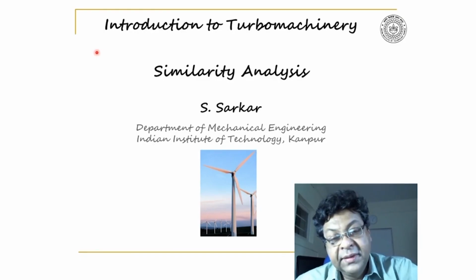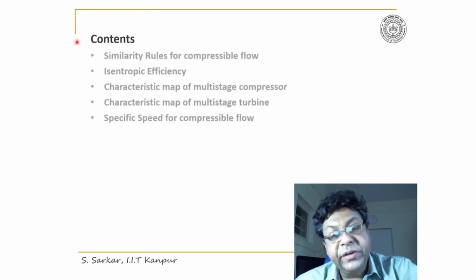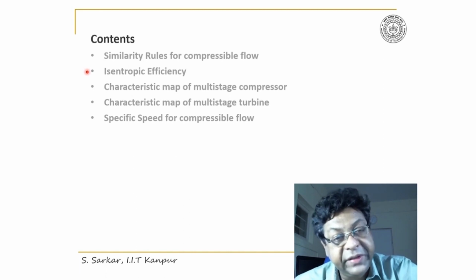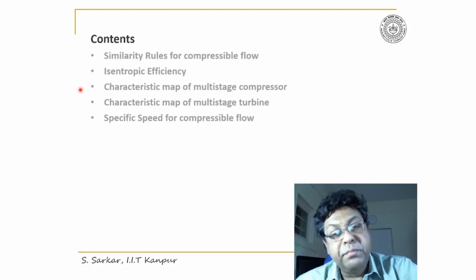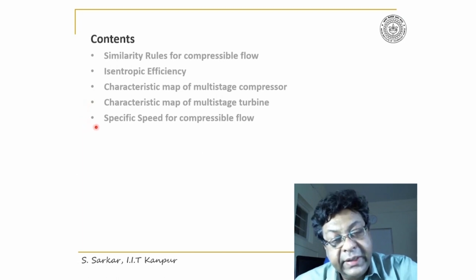Good morning. This is the third lecture on similarity analysis. The contents of the lecture are similarity rule for compressible flow, isentropic efficiency, then I'll discuss characteristics map of multi-stage compression, characteristics map of multi-stage turbine, then I'll discuss specific speed for compressible flow.